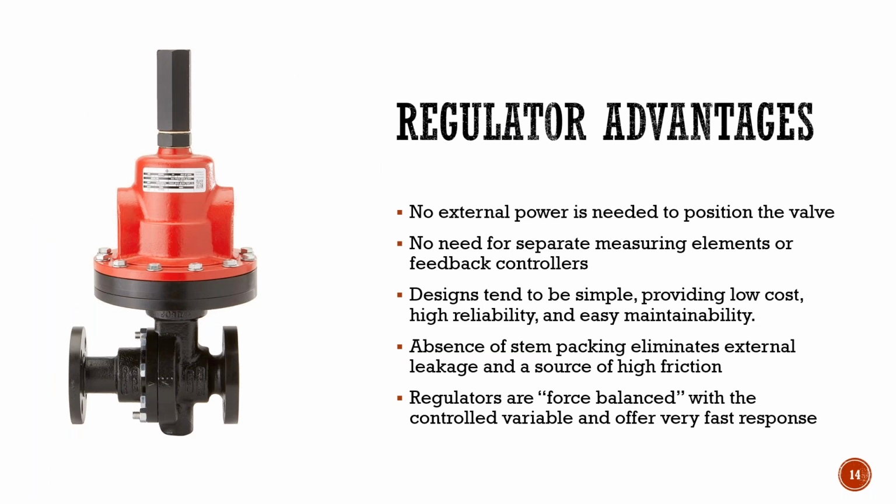What are the advantages to a regulator? No external power is needed to position the valve, okay? We call these self-operated or direct operated regulators. No need for separate measuring elements or feedback controllers. Designs tend to be simple. They're lower cost generally. They're highly reliable and in most cases very easy to maintain.